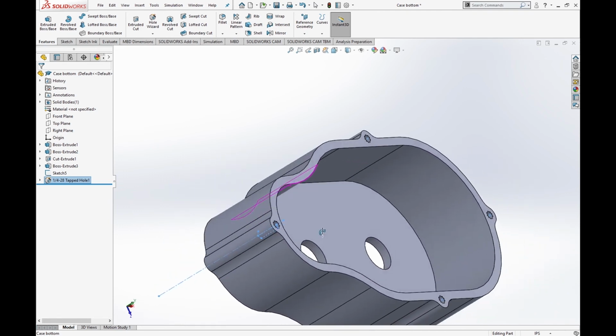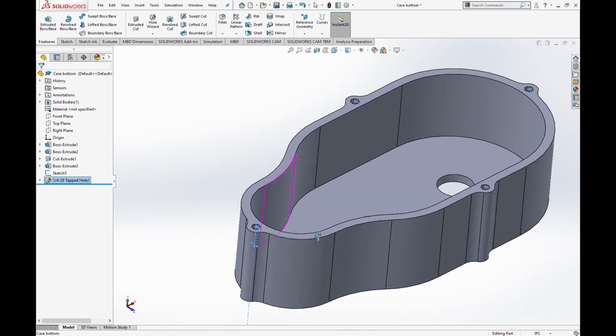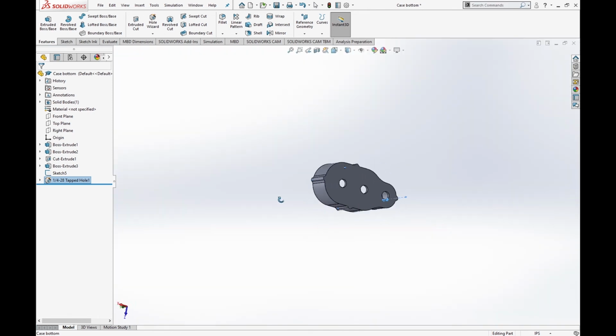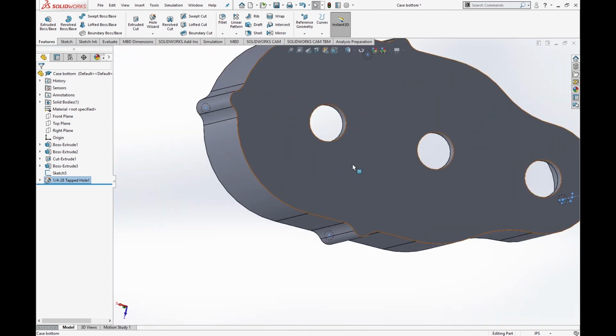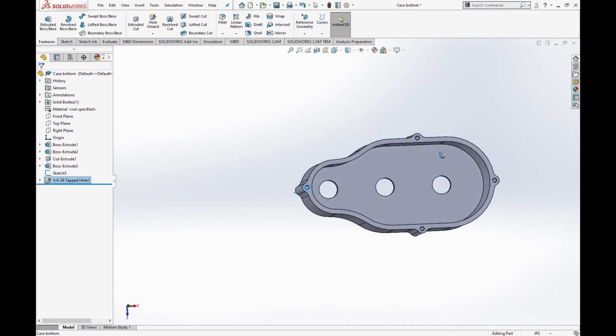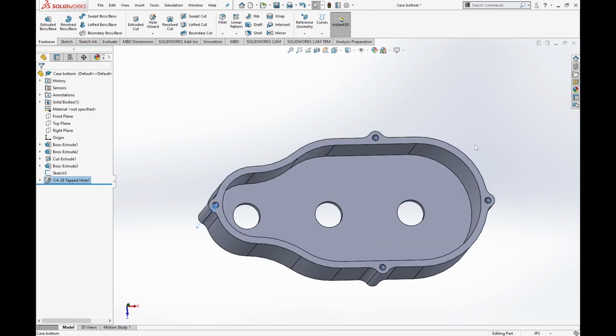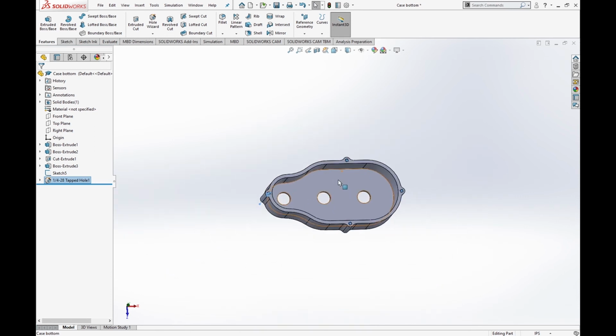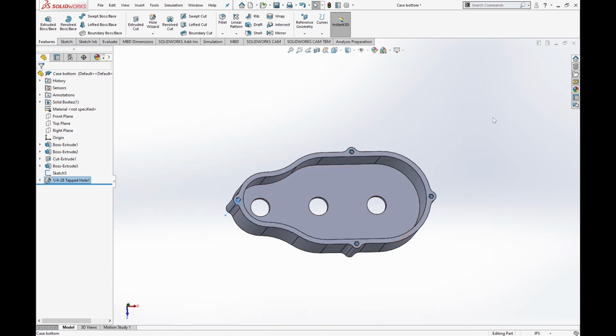And so this is close to being, we're really close. I'll do another tutorial on how to make the hats, which is what we use to keep concentricity between our shaft and our gears, and between the top and the bottom case. So I'll go through a tutorial of that later on. But right now it's just a good idea to work on this case and figure out what gears you're going to use and stuff like that. Alright, so that's the bottom case. Now let's work on the top case.